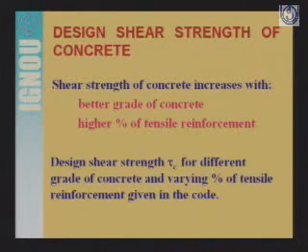So the percentage or the amount of steel also affects the shearing strength capacity, and the higher the percentage of tensile reinforcement, the higher will be the shearing strength of the concrete. So these two factors are important while designing or getting the value of the shear strength of concrete.